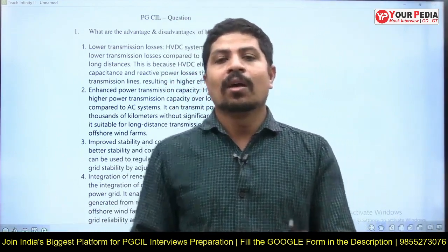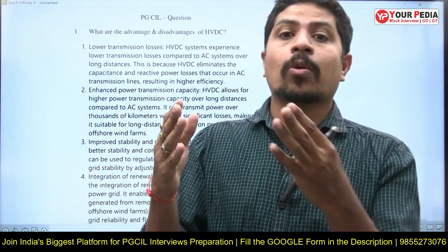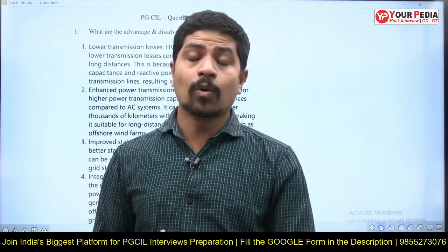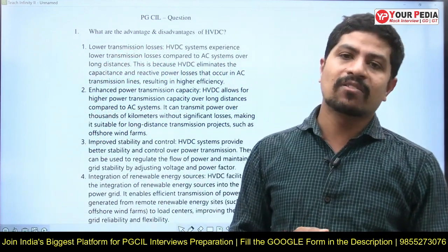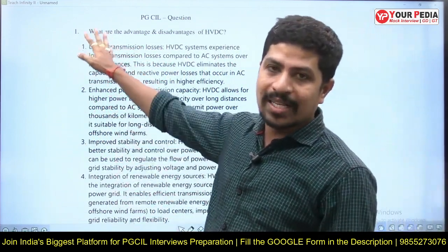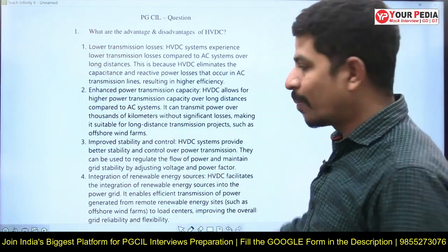With HVDC, there is no problem of stability, we know that, right? This problem of stability will come only with HVAC, not with HVDC. Power losses will be reduced with HVDC. Like that there are many advantages and disadvantages. Those are all listed here. Let's go through those one by one.